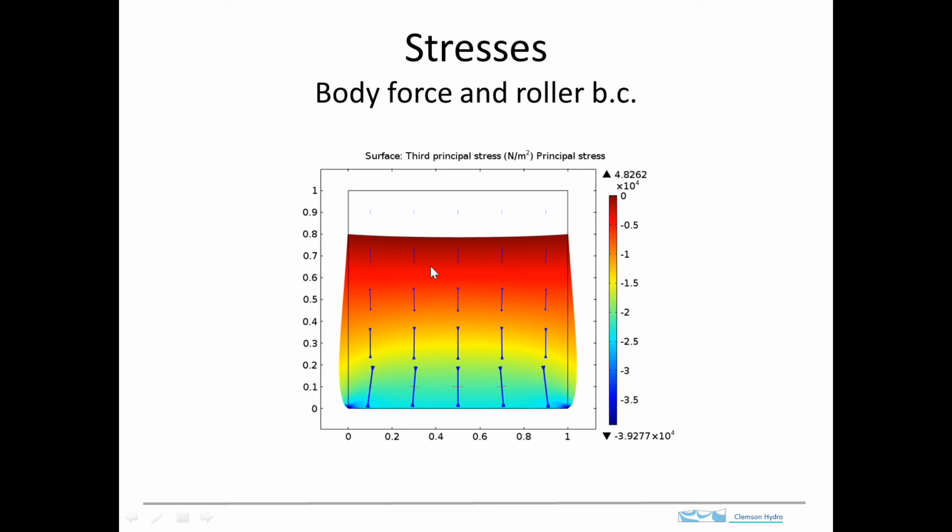We noticed up here, if we were to zoom in here, we would see very little or essentially no horizontal compressive stress, and that's because these sides here are free. They're stress-free, so the lateral stress is negligible here, essentially zero. We have some lateral stress here, though, because of the boundary condition here, because the boundary is fixed.